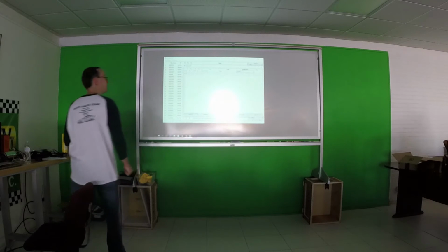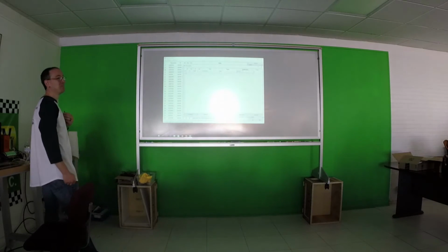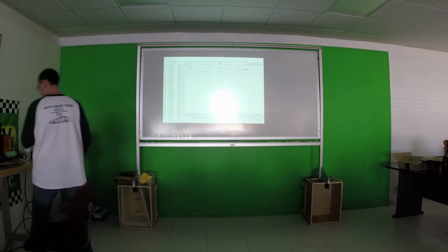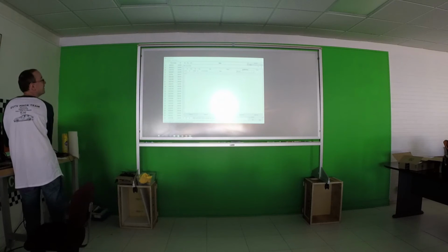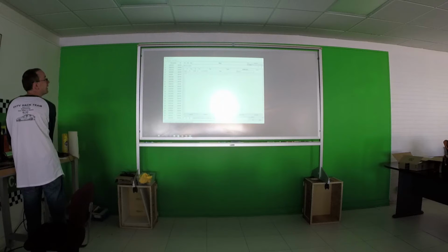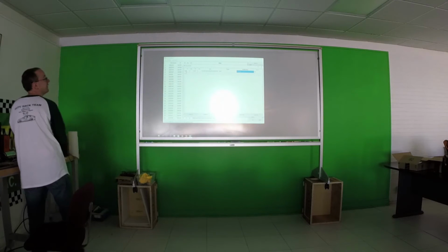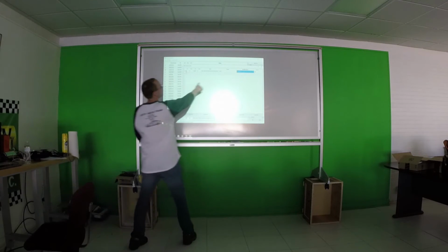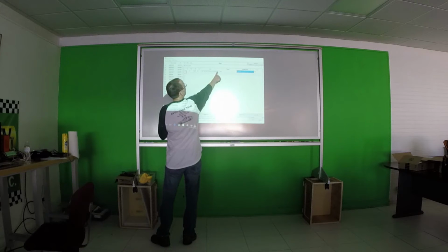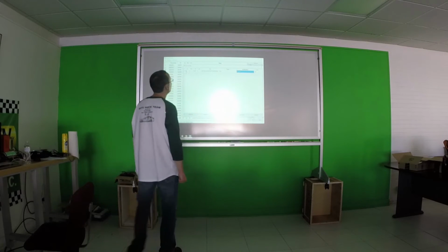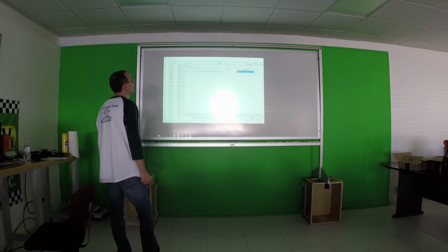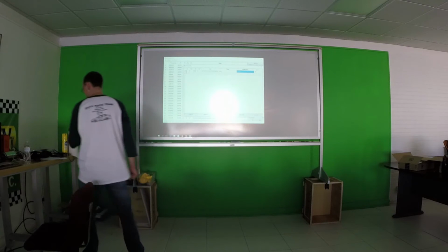I didn't know how to do that. Like I said, this is probably the most advanced section of the program because it's powerful but kind of complicated. You could also see a response from the device. I just started it. You can see what it did. It is constantly incrementing this byte now because I said to always turn that byte 1 higher every time you send. It gets to FF and